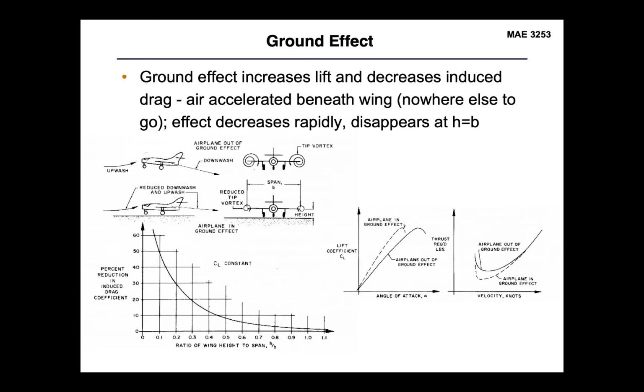Now we do have to consider in our calculation for the lift the impact of ground effect. We talked about this briefly when we were looking at aerodynamic forces. Primarily what we need to know is the distance that the wings are above the ground. The closer the wings are to the ground, the greater impact that we're going to have in the ground effect. And this is going to impact not only our lift coefficient, but also our drag coefficient.